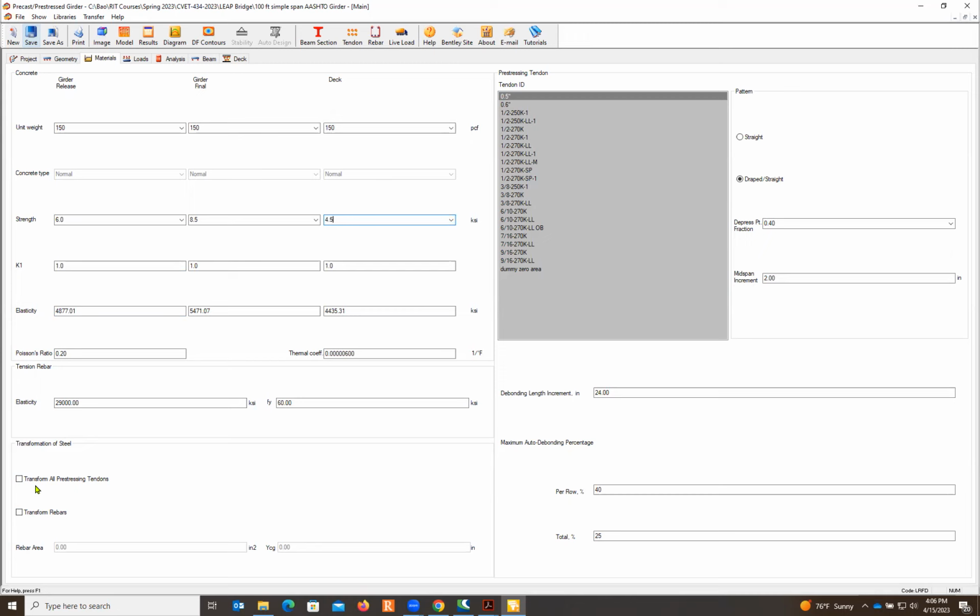And if I find that the moment of inertia needs to be increased a little based on the live load deflection at the end of the design stage, I know this is the place where I can increase the moment of inertia by some degree. So this gives me some room to increase the stiffness of the girder. But for the initial design, we just keep those empty, understanding that this part gives us some room to improve the moment of inertia.